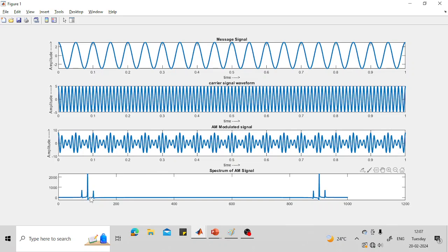Coming to here, you can observe. Previously this gap was of 10. Right now this gap is of 20. If it is 100 hertz, then this is of 120. You can easily observe the x axis, x is 100 here, right? Now observe here, what is x? Just a second. Yes, what is x? 121. Fine, means 100 plus 20, that is fc plus fm.